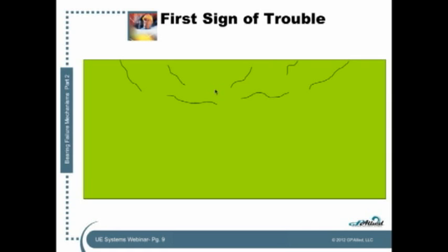And the very first thing they do is they reach up and turn that volume or sensitivity down. And when they turn it down, they hear that the pattern is still very smooth, doesn't sound rough, doesn't sound random. It's very smooth white noise, and they go, oh, it's just louder. Well, the bearing's actually trying to tell them something. The bearing's trying to tell them one of two things: A, I need some grease, or B, I've got subsurface fatigue.